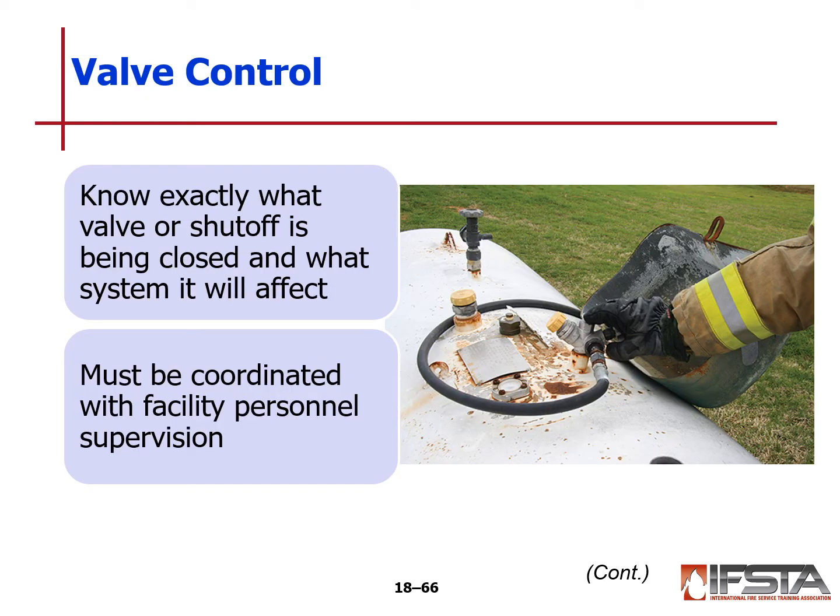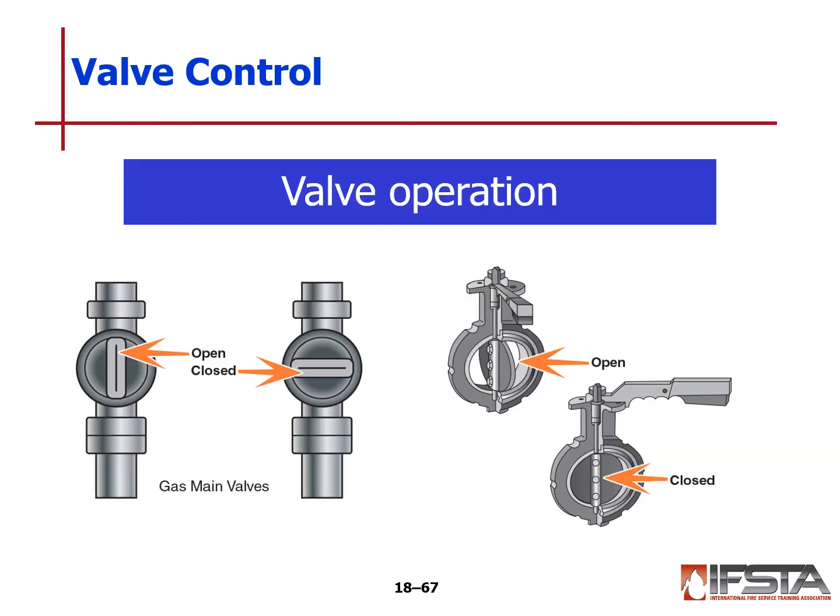We may control using the control valve. Know exactly what the valve or the shutoff that is being closed is, and what system it will affect. And this must be coordinated with the facility personnel or supervision. So we have to kind of know how to operate these valves.